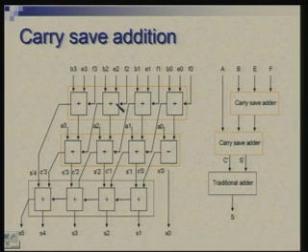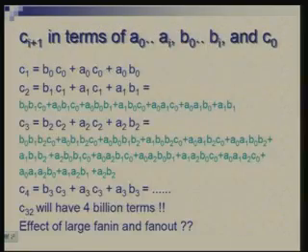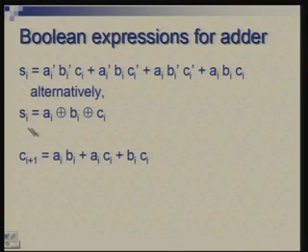So, if you really see, let us go back to this expression of the sum, or even if you look at that, it is symmetrical with respect to A I, B I and C I, right. So, it is only our interpretation that one of these we are calling as carry input, but as far as circuit is concerned, you can think of this as a 3 input and 2 output adder. It reduces 3 inputs to 2 inputs, and these inputs are interchangeable.